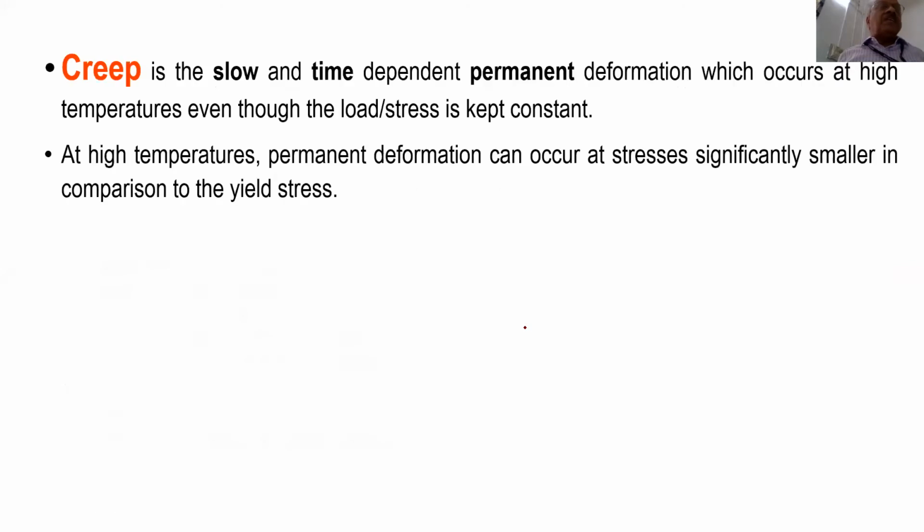Now creep is yet another important property. Dr. Ishwar Prasad mentioned creep, because creep is not so common unlike tensile or impact studies, because creep is a little bit more complex and it is very expensive also. So creep represents the behavior of a material under constant loading. In tensile, you are continuously loading. In impact, you are continuously loading. In fatigue, you are cyclically loading. Of course, you increase the load and then you reverse it. Whereas in creep, the load is kept constant. Still, the material will deform, damage, and fracture after a certain amount of time.